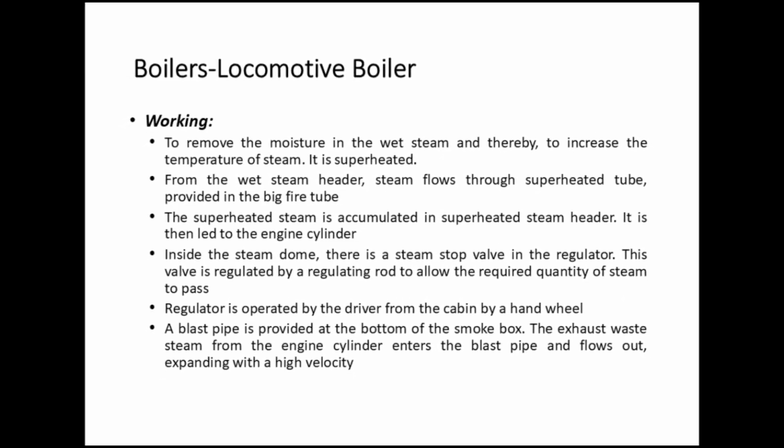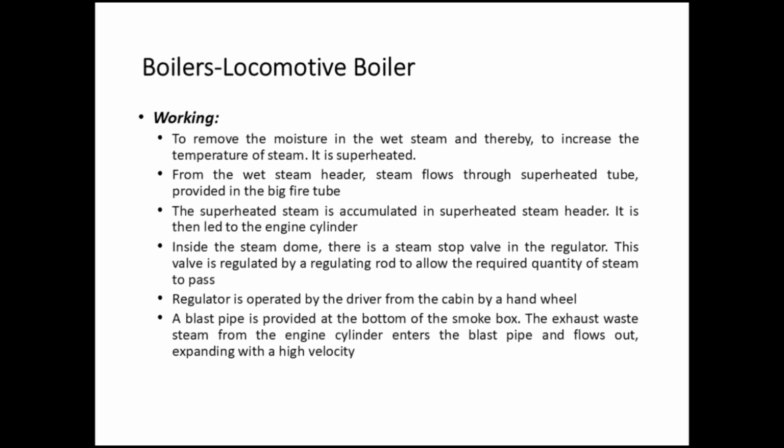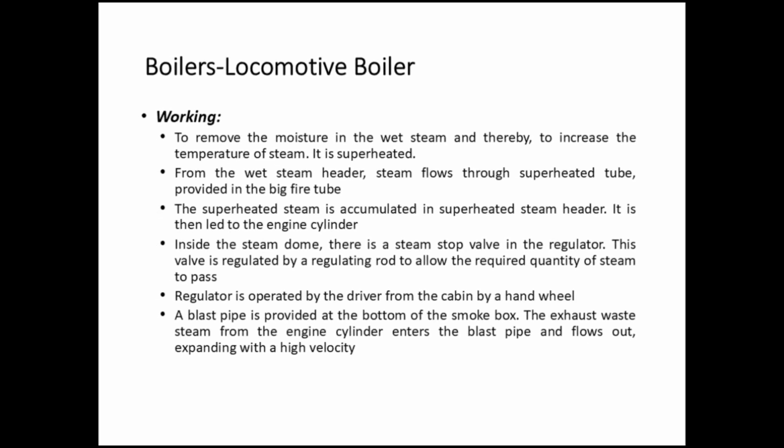Boilers. Locomotive boiler. Working. To remove the moisture in the wet steam and thereby increase the temperature of the steam, it is superheated. From the wet steam header, steam flows through superheater tubes provided in the big fire tube. The superheated steam is accumulated in the superheated steam header. It is then led to the engine cylinder.